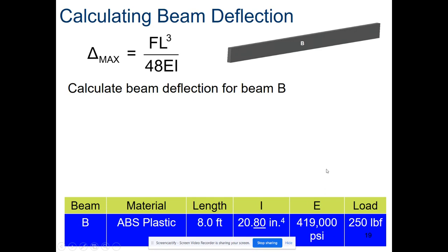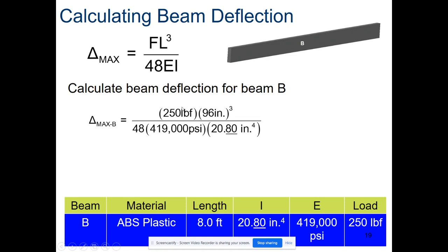So if I go ahead and plug those numbers in, everything's the same except for this one number. And that's going to make my denominator a lot smaller, which makes the overall fraction, this calculation we're going to do, a larger value. And so when we divide that, we're going to get 0.53 inches. So we've gone from about 1/8 of an inch up to a little bit more than a 1/2 inch of deflection. So it's going to bend a lot more. Definitely going to notice that.